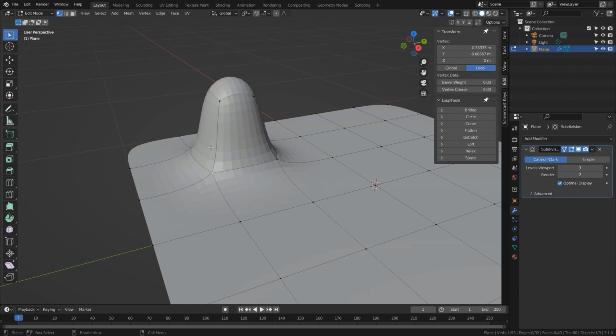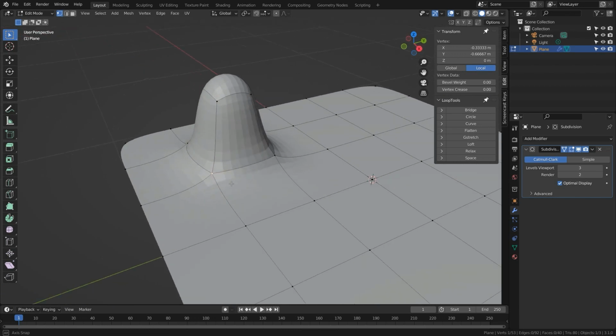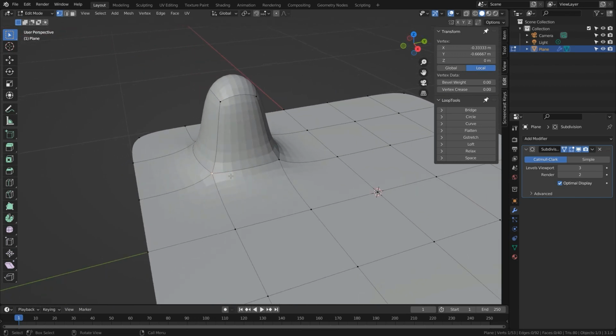As we can see, we've created these 5-spoked poles, and they live on the area of maximum distortion within our geometry. It's the worst place for them, which makes future modelling tasks around this point tricky, confusing and difficult to control. Now it will cause some minor rendering issues as it is, but that's not the main problem. The topology looks a little unnatural, but again that's not the main problem either. The curvature spreads out to whatever the next row of edges happen to be, and that is slightly more of a problem.